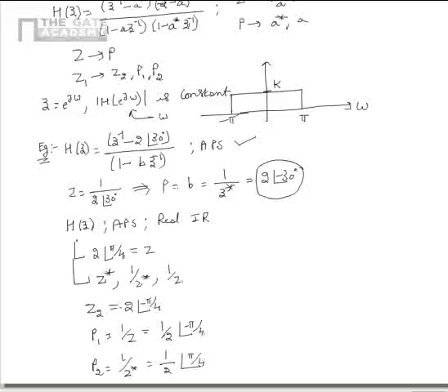From this we see that depending on whether the system is all pass and depending on the nature of the impulse response, given the location of a zero or pole, we can find the location of other zeros and poles.